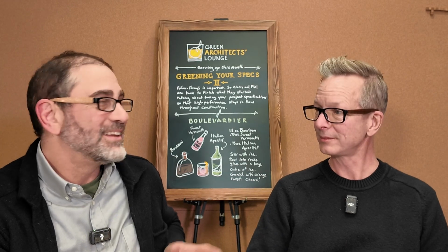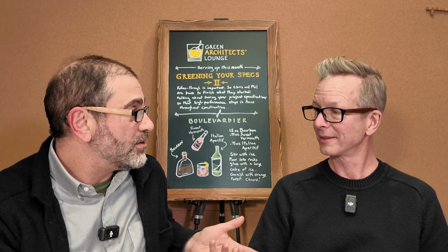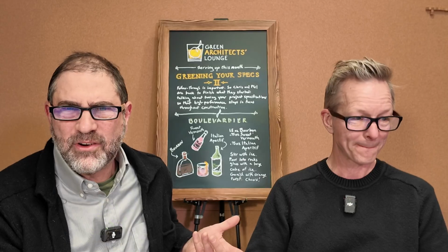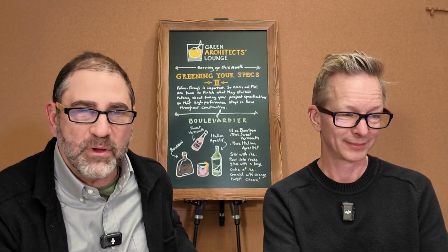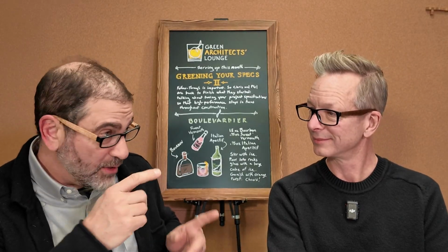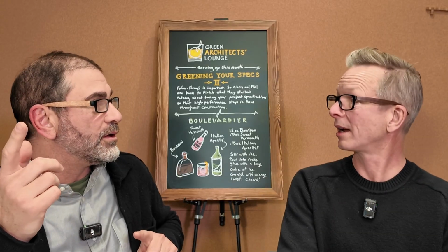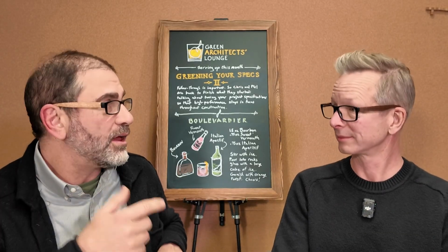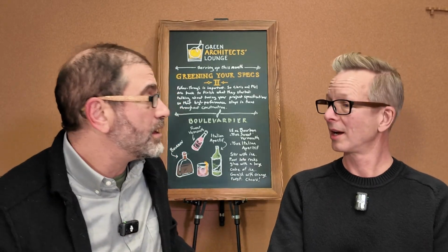That's good. I'll tell you another thing we put in our specs too, and we get it in our drawings too, but I realize now that since it's in our specs, we might as well mention it: all plumbing vents have to be in the top third of the roof. Yes. And to consolidate when possible. And consolidate when possible, yes. Because a lot of times... Well, we have this here.